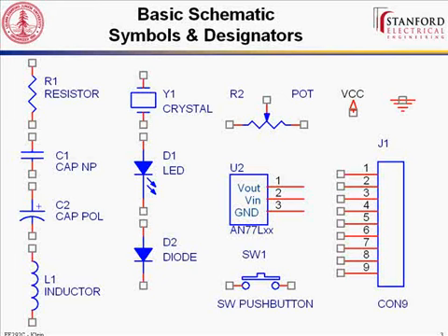So if you look at the schematic for your development board, there's a 3V0 or 3V3, indicating a 3.0 or 3.3 volt rail. And there's another one that's labeled 5V0. That's the 5-volt rail. But they both have the little arrow shape. So you use those to indicate what lines are power rails versus just signals going around.